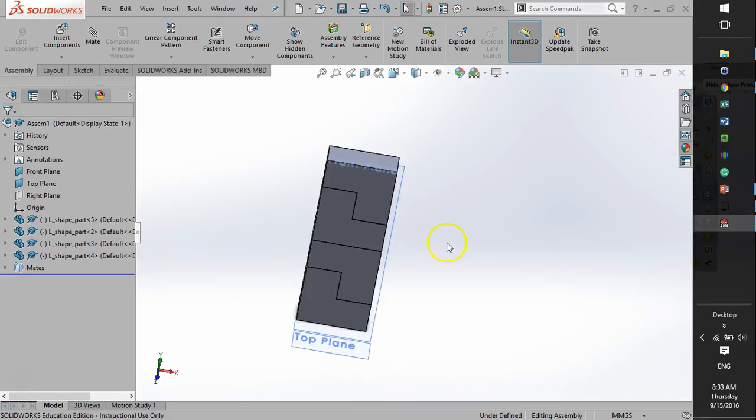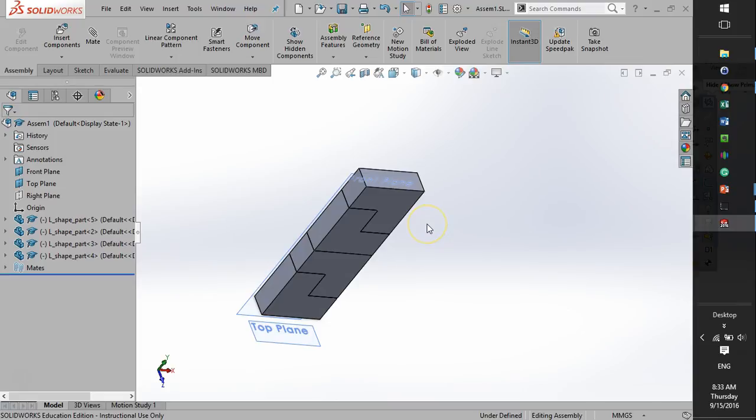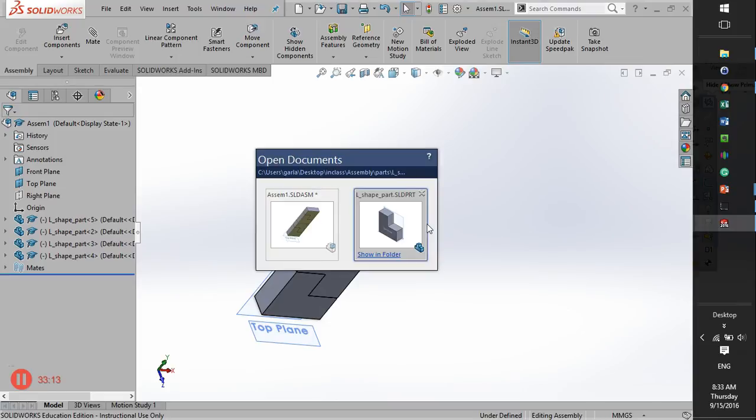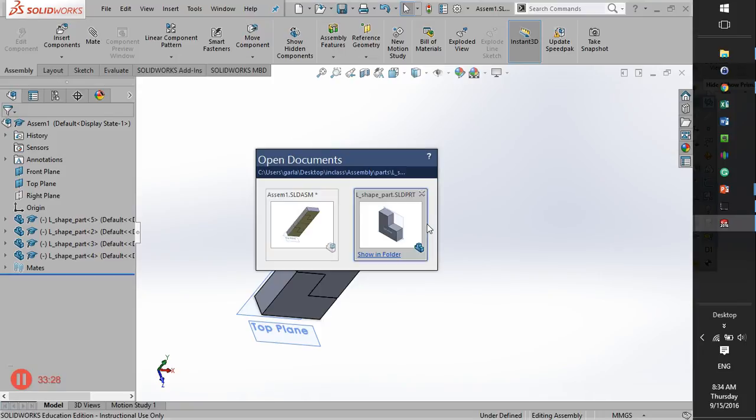If you didn't already know that, that's a quick shortcut for you within Windows. Within SolidWorks, there's something similar. If I hold down Control and hit Tab, it's going to bring up this document. Right now you can't see, but I'm holding down the Control key. And then every time I hit Tab, it's going to toggle between the two open parts. Then when I let go of Control, it's going to actually go to that part.